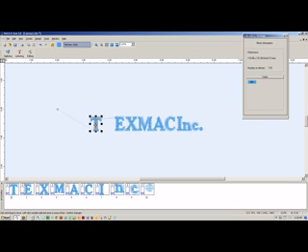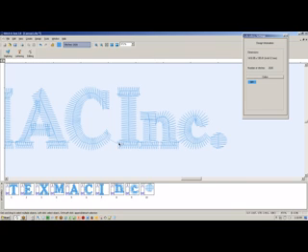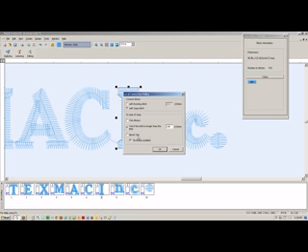But let's say you don't want to mess with the connection policy, you want to just go ahead and add a trim in. For example, you can see that there is no trim between the TextMac and the INC, whereas it may be okay to leave that little stitch in there. But at the I, I would absolutely trim there. So you can right-click, go to Edit Connection. You'll see a similar window pop up, but this is called the local connection policy.